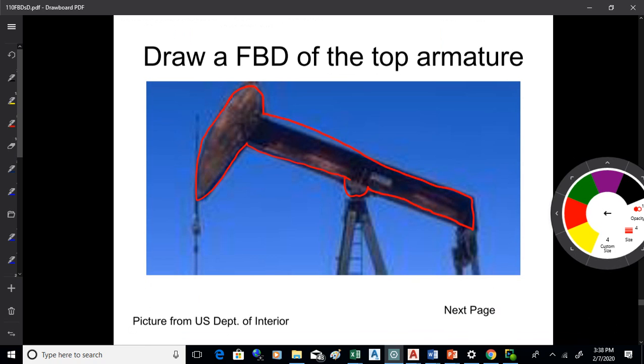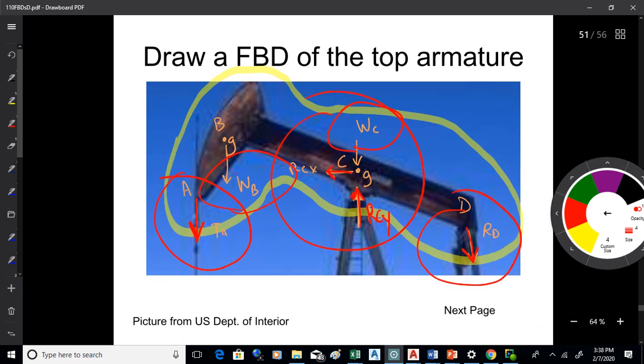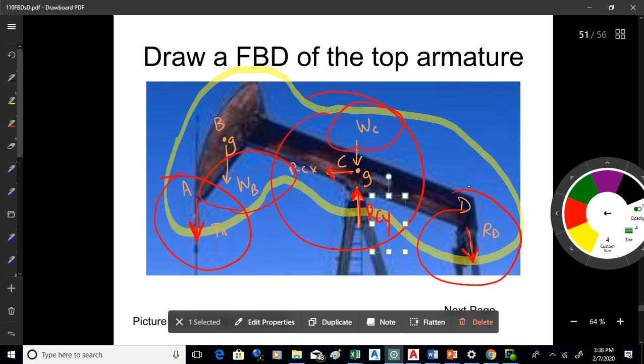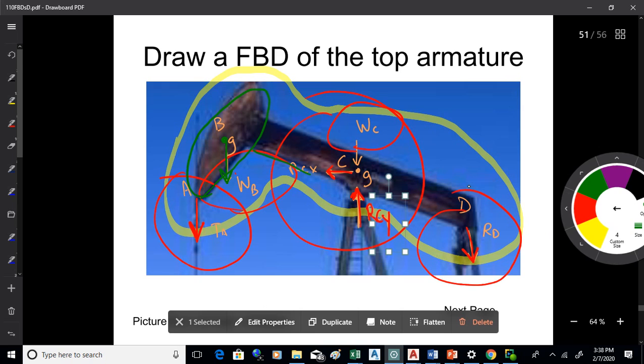And we don't care about the weight at D, at the very bottom end? Well, what I did is somewhat arbitrary. I decided to say I've got 2 pieces to this mechanism. I've got this piece, and I'll put its center of gravity here and put its weight there. And then I've got a beam. My beam, I said, is here, and I will put the entire weight of the beam at its center of gravity. That's kind of how I chose to handle it.